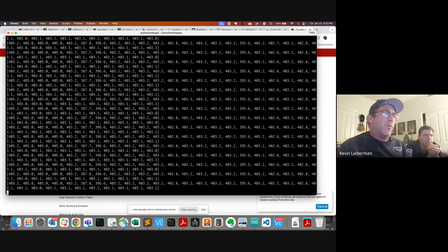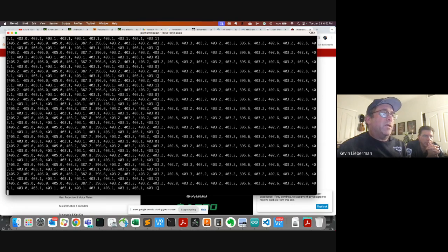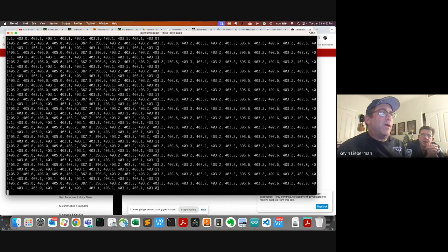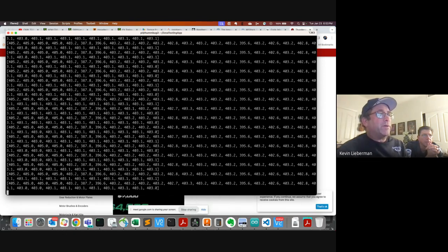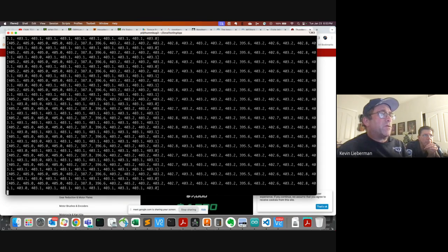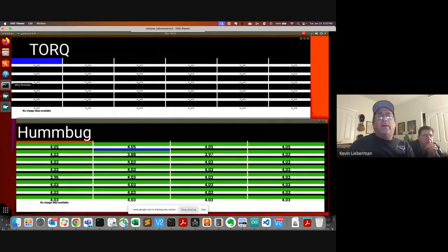But it's all getting data in the same way, through another protocol commonly used with IoT, or Internet of Things, devices called MQTT. So all the data that I'm gathering over CAN, I'm also broadcasting over the Wi-Fi network coming from the Humbug to whatever is around to listen to it. Sometimes it's my phone and sometimes it's the computer in my garage. So it's receiving these messages, which you see scrolling by on my screen right now, and showing the display in a more graphical fashion here on the screen.